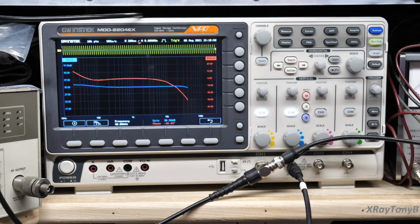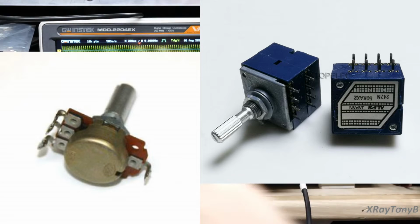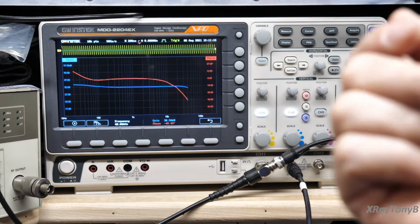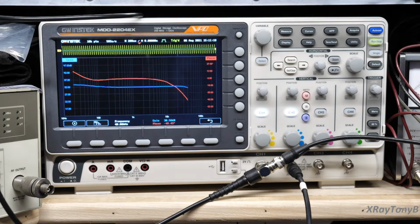Remember, you ever hear about a pot having a loudness tap on it? In other words, you've seen a potentiometer with 4 pins instead of 3 pins. So you have the lower pin, the upper pin, and then the wiper. And then you'll have that 4th pin. And they call that the loudness tap. And the loudness tap is actually a connection a little way up, about 1/4 of the way up, or 1/3 of the way up, something like that, on the potentiometer itself. It's just a fixed tap.